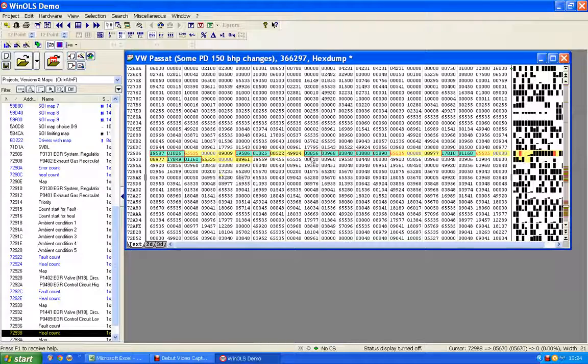And what I could now do is load this file into the car and go and see if I get any errors. Because obviously if I get any errors, I'll either get the MIL light come on the dash, or the MIL light won't come on, maybe, but when I do a scan for errors, I might find that I've actually got errors displayed.